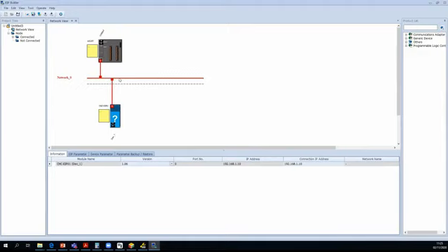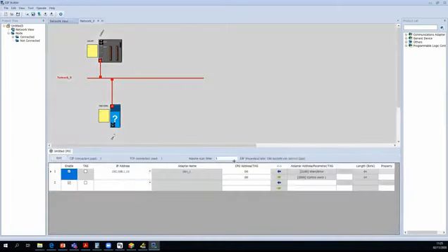So now we'll go to data mapping. And this part is maybe not so intuitive. Sometimes it might be more difficult to find, but you need to move your mouse cursor in this area and then right click on the PLC and click data mapping. So here I can define my input and output registers on the AS300. And here you can see the corresponding registers on the C2000.